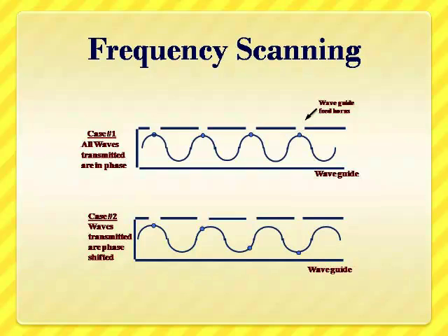So you can see in this diagram, suppose we have a waveguide feeding a set of horns at different locations. If we place them exactly at lambda g spacing, then the wave that is going to excite these horns can be adjusted to give in-phase excitation by adjusting the electrical length between two successive horns as 1 lambda distance. So in the diagram here, you can see the peak of each wave is connected to the